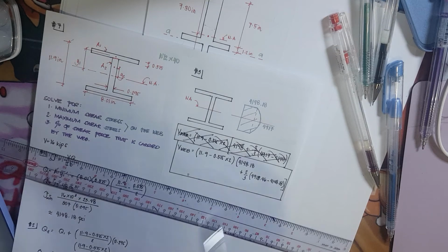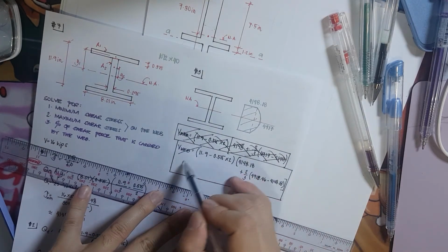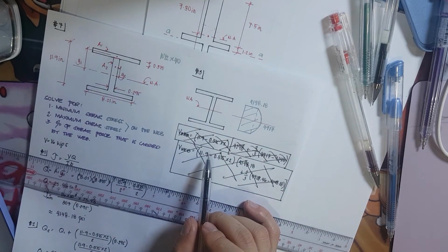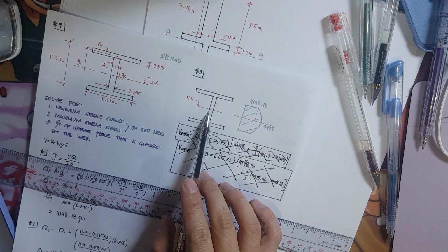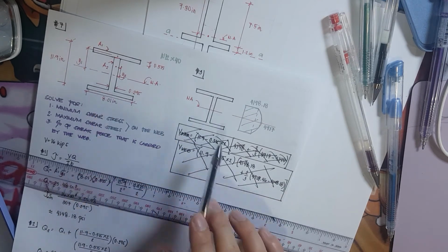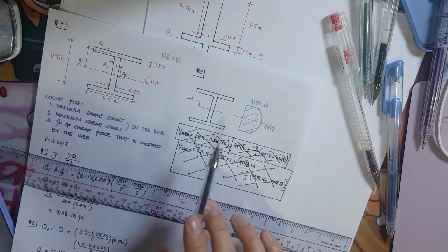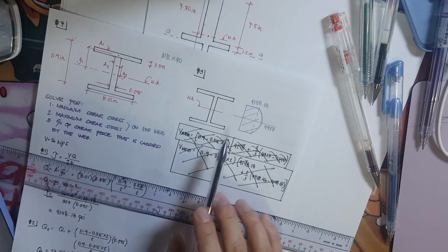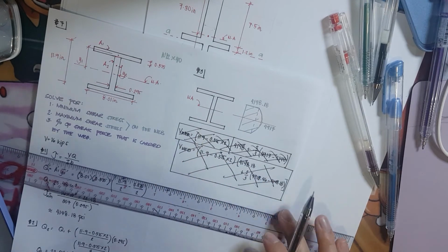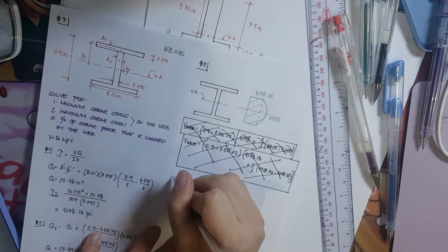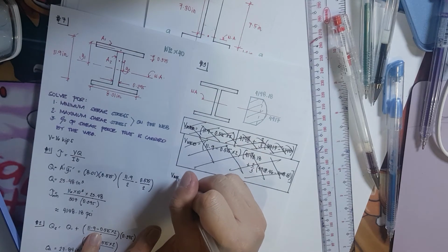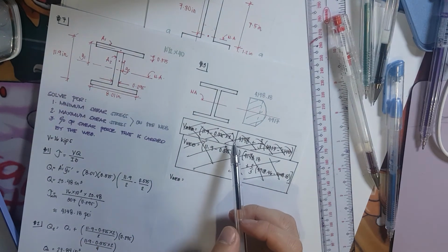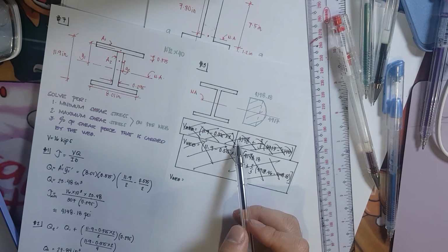erroneous. So the shear on the web that we're trying to solve is erroneous. Why did I say so? Because take note that the thickness of the web is 0.295 already, but what I am using is 0.515, and that is the thickness of the wide flange. Okay, so that is erroneous. So I repeat, the shear of the web is equivalent to the wide flange here. Okay, I forgot to multiply here the thickness of the web.